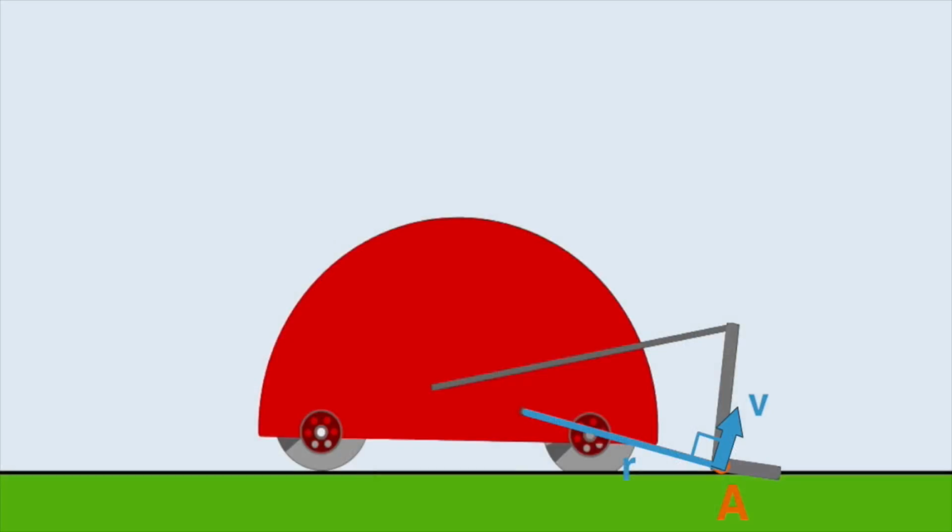It can't be towards the pivot point because it's a rigid body. So if it moves, it's going to move perpendicular to that radial line from the pivot out to the point. And we can calculate that tangential velocity at that point by simply multiplying the radius times the angular speed. The angular speed would have to be in radians per unit time to do that. So that allows us to quickly determine the velocity at any point along the link. In this case, we're interested in point A.